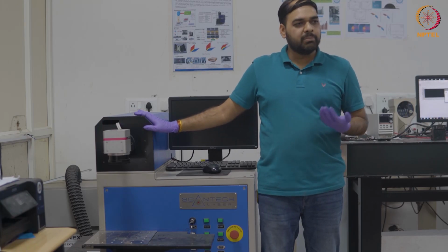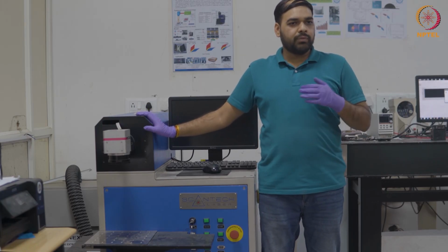So the flexible micro actuators, after the deposition, are fabricated using laser energy with a fiber laser. So why are we using it? Because we want to make flexible actuators of customized size. Generally, for thin films, laser energy is a very high energy thing for machining, so it either burns the film or damages it. With a fiber laser, the energy and the direction of the laser can be easily controlled to get the customized shapes.